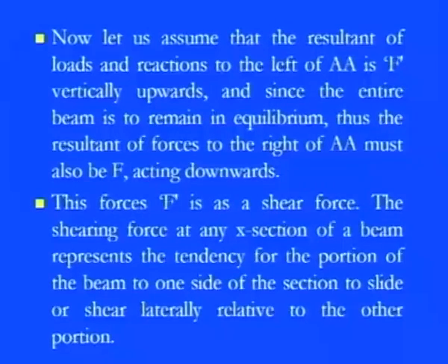So that's why we can say that this beam, under the application of these applied forces and reaction forces, is in a well equilibrium manner. So this force F, which we are saying is the resultant force, is nothing but the shearing force, because this force is the resultant due to P1, P2 from the upward direction and the reaction force from the downward direction.